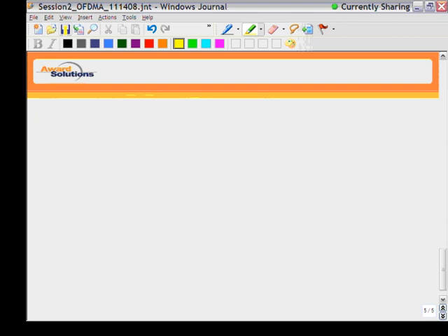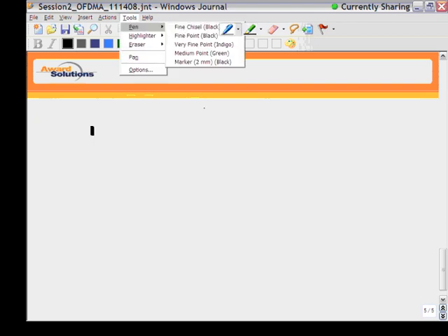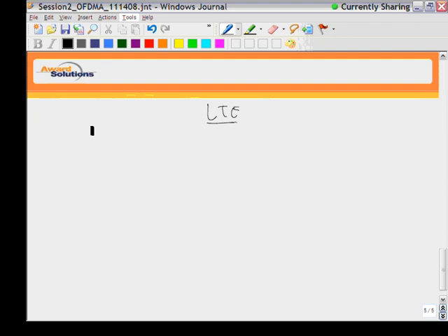Now for LTE, let's talk about a user, and we give the user in the downlink two sets of carriers. So let me draw a picture here. So one user. Now I'm giving you the answer for LTE, because you asked the question, can the subcarriers be non-contiguous? So the short answer is yes, they can be non-contiguous. But I need to give you a little more detail, otherwise my answer will look incorrect.